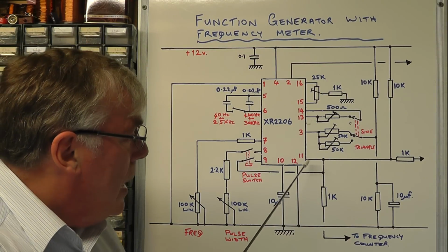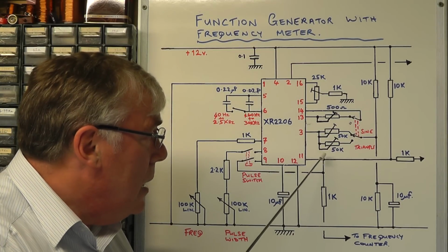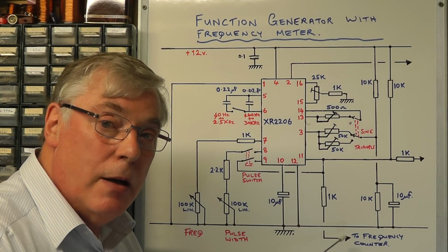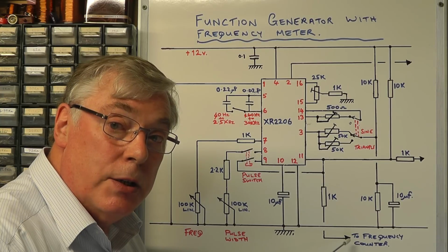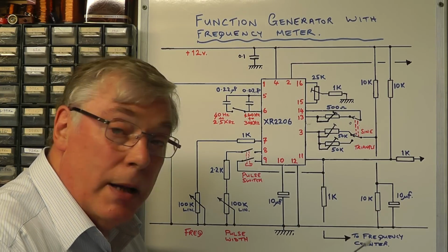Now on pin 11 there, which I mentioned is where we have our square wave coming out at that frequency, I'm also tapping that off through a 1K resistor to feed that to our frequency counter circuitry on this project today, and I'll come back to that shortly.